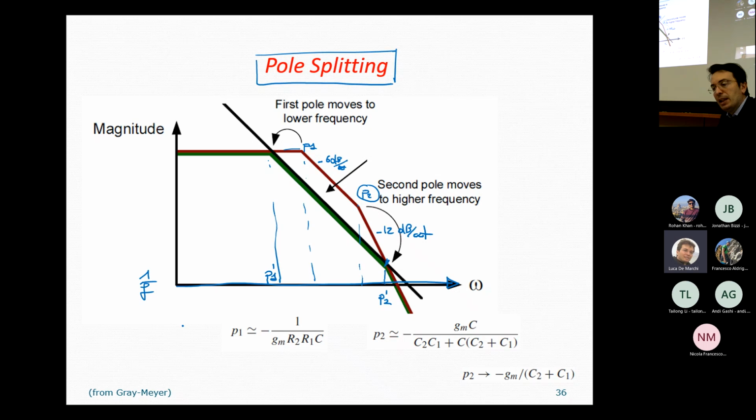Okay, because when we pull down this node, then the increase of the output voltage is very rapid due to this quadratic phenomenon. Okay, so the problem of studying the derivative of the output with respect to time can be transferred to the study of the derivative of the VD2 value with respect to time.